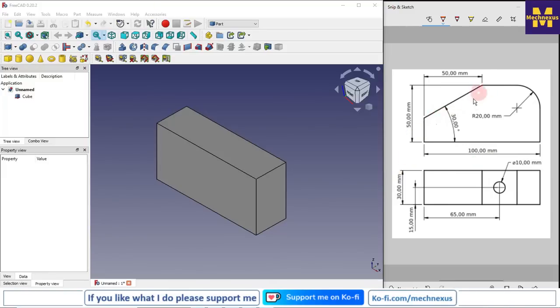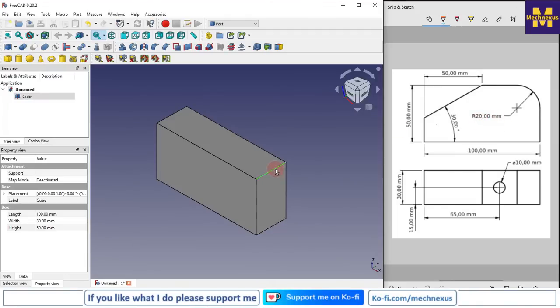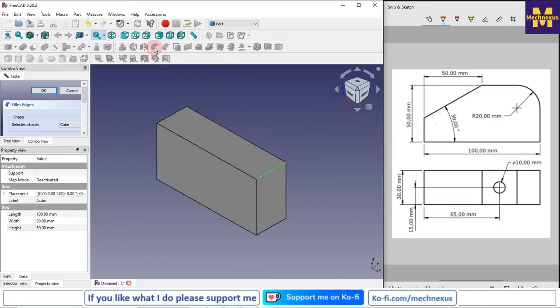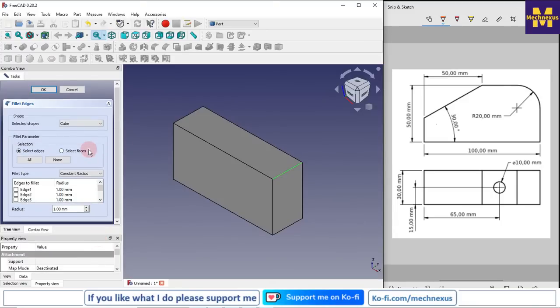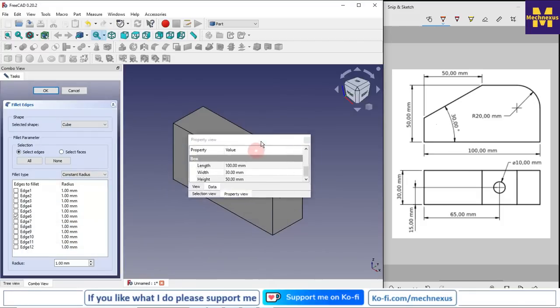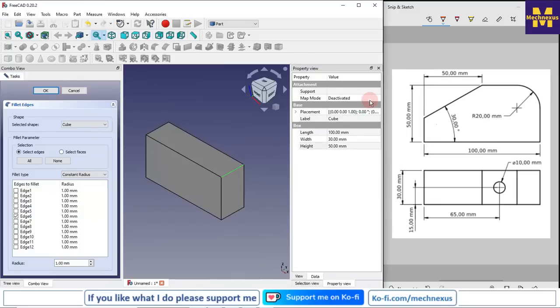Now we will make this radius R20. So we will select this edge and here is an option of fillet. So we will click on the fillet. Now if you are facing any difficulty, then you can move it to the other side.